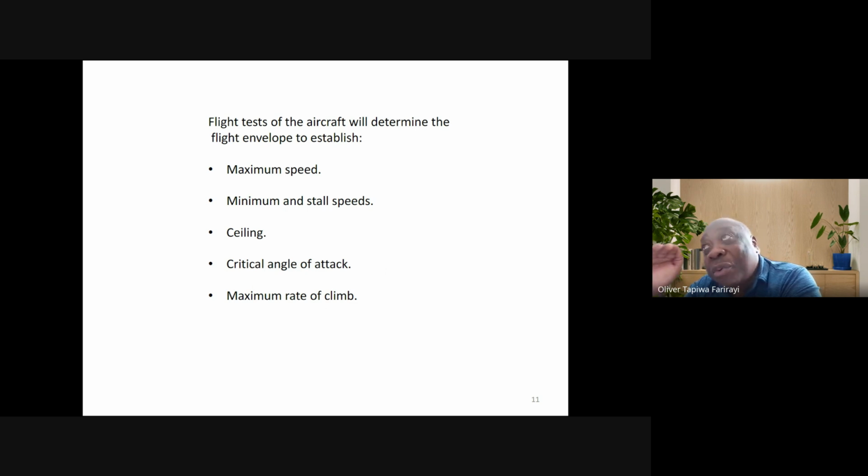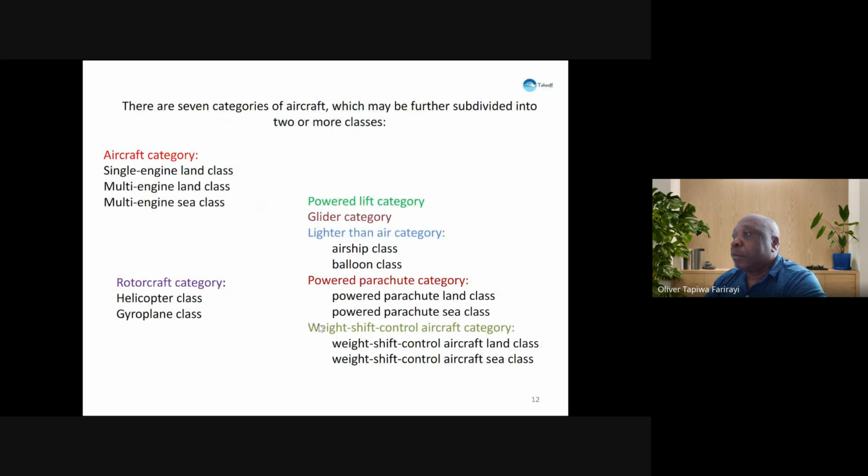But what it tells us also, once you reach levels like 350, 370, your maximum rate of climb is going to reduce drastically, almost to crawling speed. So you have to be careful if you are using that separation. Remember, a level vacated can be allocated to the next aircraft. You have to be very careful up there, especially if the aircraft are one on top of the other or too close in trail.